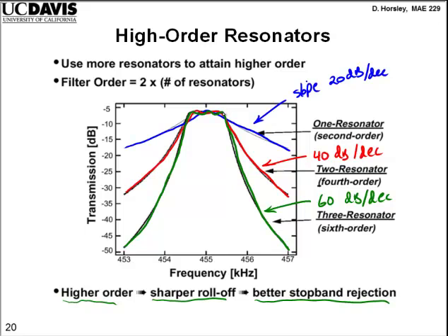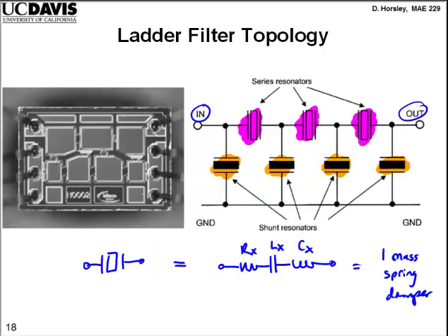And so we can have a nice flat passband, and we can have sharp skirts on the sides. Okay, so that's the idea in these things. Those are the kind of responses you would get if you just had resonators coupled in series. Now, if you look back at the ladder filter, a ladder filter also has these shunt resonators, and